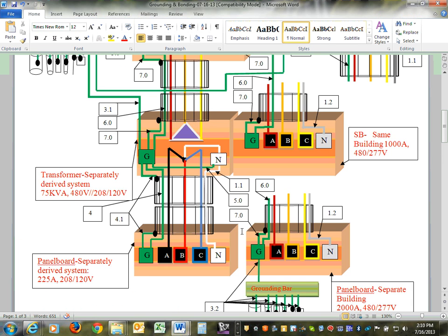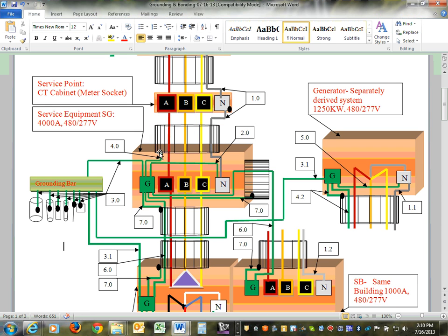So that's what I thought. Do you guys think of any scenarios that are not here, commonly used, other than DC and high voltage? Do you guys encounter any scenarios that are not here? There are scenarios where you can bond, there's a lot of other bonding that we use. It's HVAC equipment. The grid here has to be bonded. But these we bond based on the closest overcurrent protection device to them.